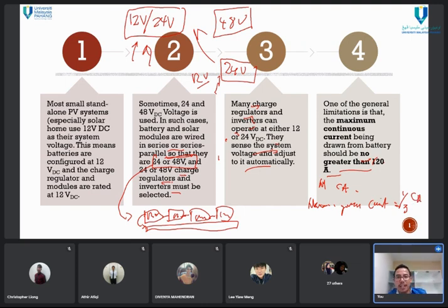If the capacity is 100 Ah, the maximum injected current or maximum charging current is actually 1/3 of that, which is 33.3 A. If it is a 3Ah battery, the maximum injecting current or maximum charging current is limited to only 1 A. Remember this.